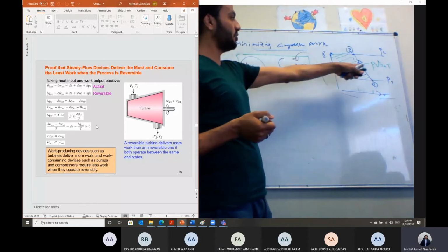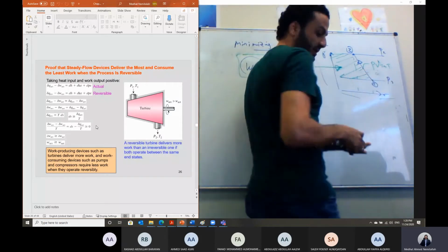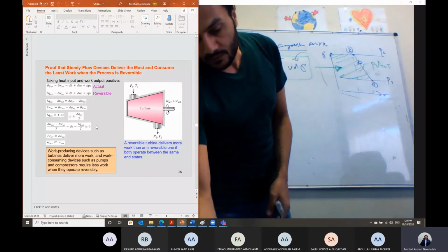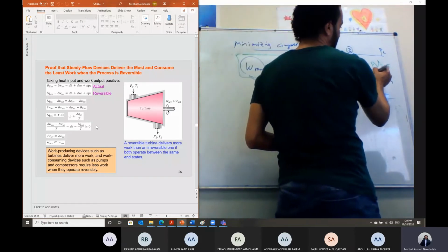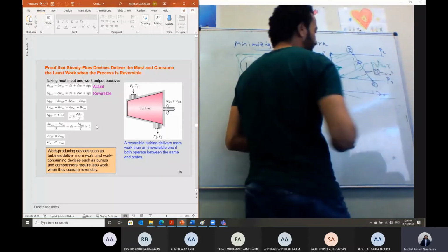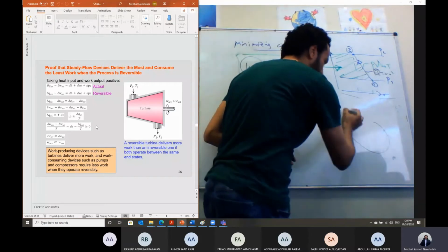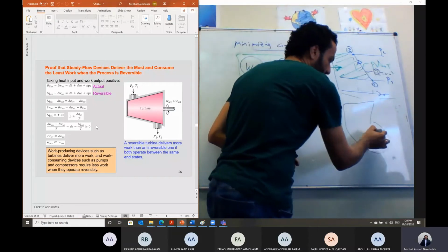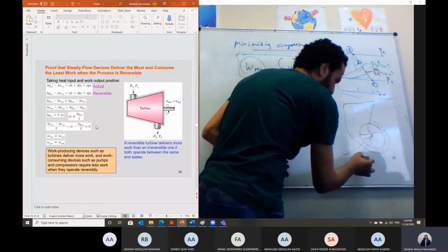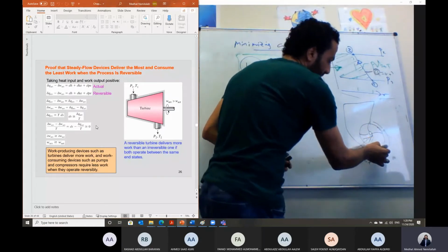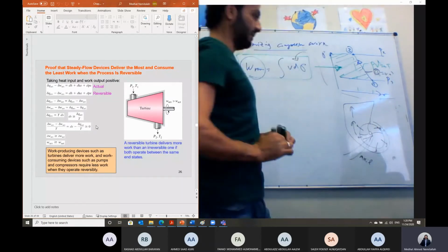So we said for the isentropic process, this process is what, guys? Adiabatic. So we don't have what? Do we have heat transfer? So this process is adiabatic. But what will happen when you compress the gas and we don't have any kind of heat losses? This is the compressor here, and these are the blades here. The flow is coming here in the axial direction, and it is leaving in the radial direction between the blades. It's collected here and going out.